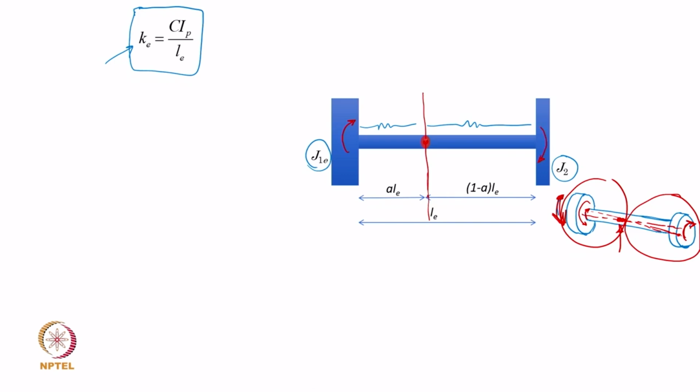Okay, so essentially this part will act like a single degree of freedom system, and this can be considered fixed, and this part oscillates like another single degree of freedom system. Both of them will have the same natural frequencies. Together they do still constitute a 2 degree of freedom or a 2 mass or a 2 inertia model, and our job is now to carry forward and figure out what is the expression for the natural frequency.